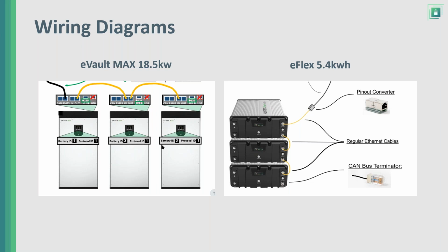There's a procedure to connect to the battery bank and say, we are communicating with an Envy, with a Schneider, with a Solar. It's done inside the battery, and it's done once, and that's it. It doesn't matter if you turn off the batteries later on. That information is going to be stored, and it will become permanent as part of the configuration of the batteries.